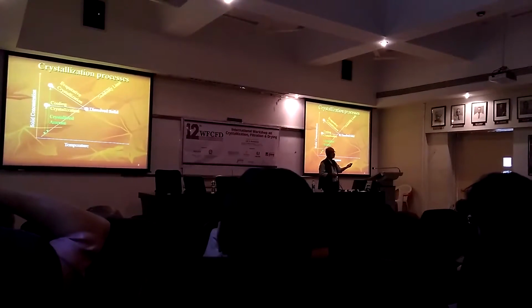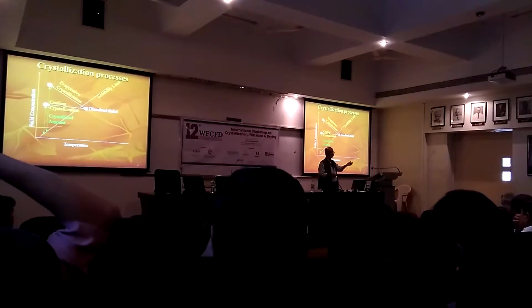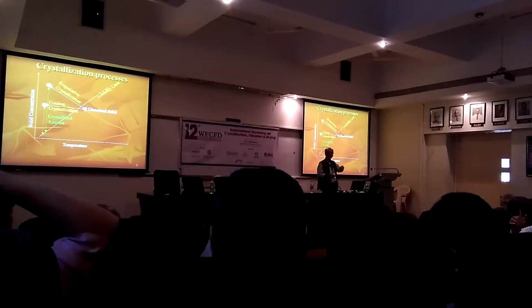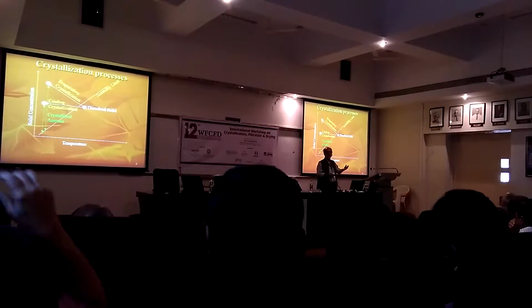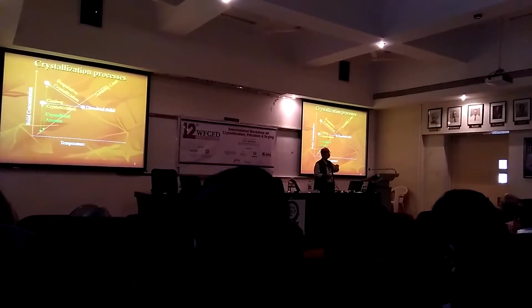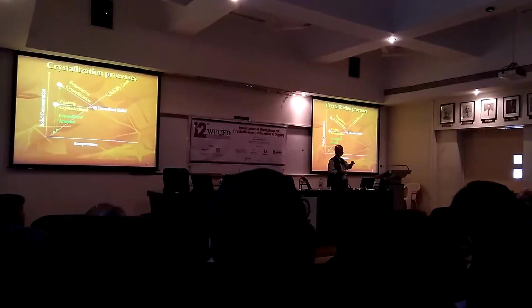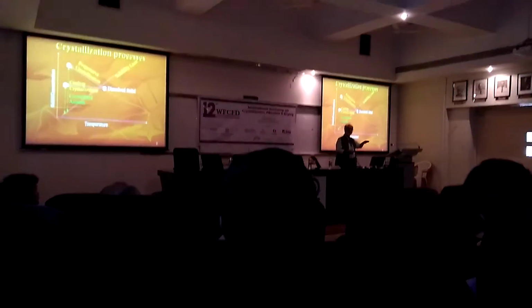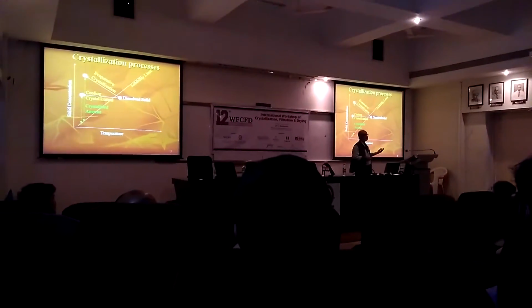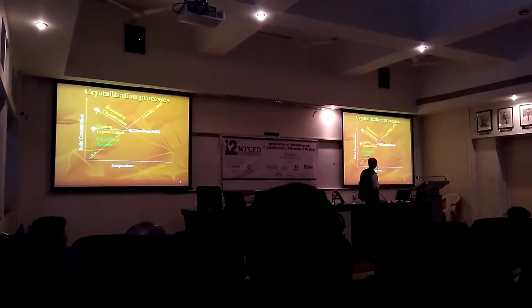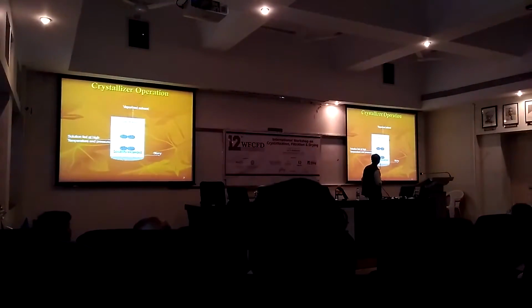Just evaporation, because your mother liquor is at a higher temperature, it will have a higher solubility. You will not be able to recover the same quantum of product if you do not cool it. So just evaporation is rarely practiced, but evaporation followed by cooling is the system which is operated to get enhanced recovery of the solute material.